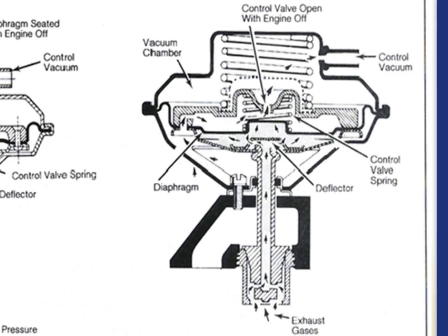The positive back pressure system valve uses exhaust pressure to regulate flow through a vacuum control valve. The stem of the EGR system valve is hollow and allows back pressure to enter the bottom of the diaphragm. When sufficient exhaust back pressure is present, the diaphragm moves up and closes off the control valve. This allows a full vacuum signal to be applied to the upper portion of the EGR system diaphragm, which opens the valve.